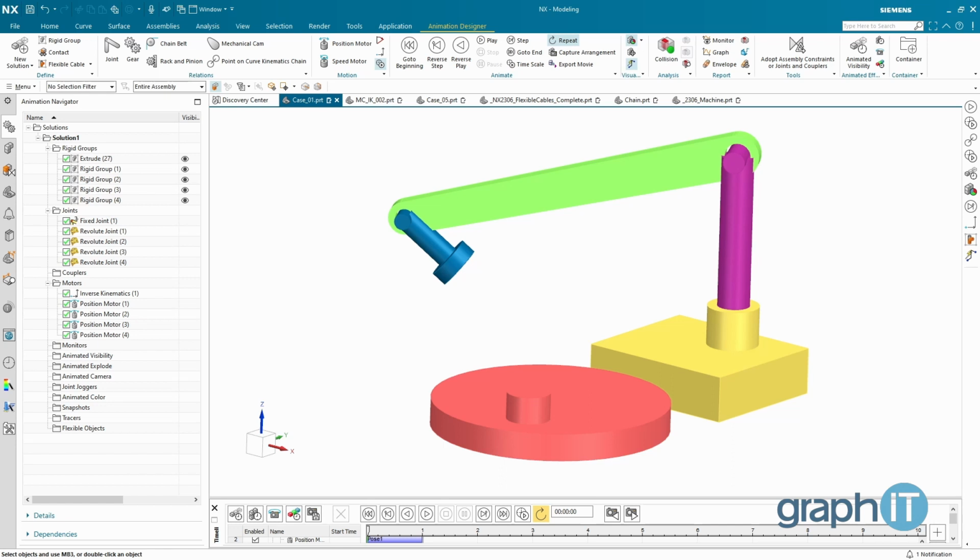Technically there are two solutions here. That platter could be in two different locations, but there's a very limited number of solutions. In this case, inverse kinematics will solve the nearest solution, and that's what it will return. Keep that in mind. If your system has infinite numbers of solutions, inverse kinematics won't work.